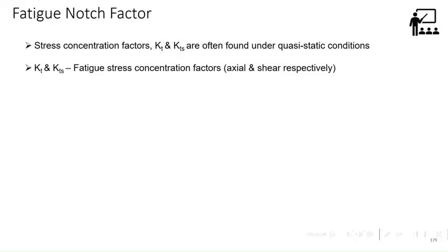That is one thing. The second thing is that nowadays everybody asks me to correlate experimental data with theoretical data. Experimental data means the specimen or structure actually experiences, due to its own alloy and whatever characteristics. Then on the theoretical side, if you don't take this small correction factor, the fatigue stress concentration factor, you will never be able to match with that. There will always be a difference. So for these two purposes you need to know it.